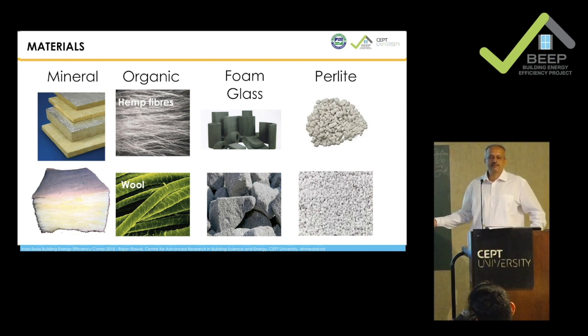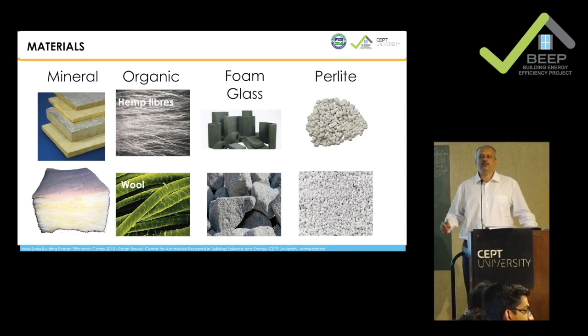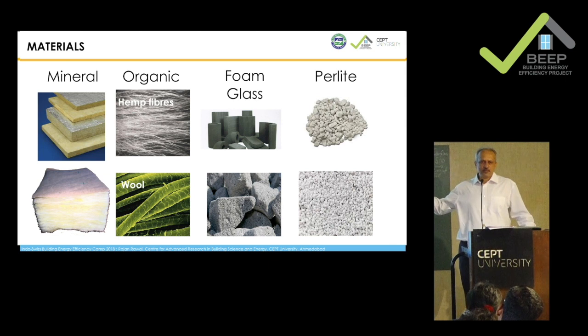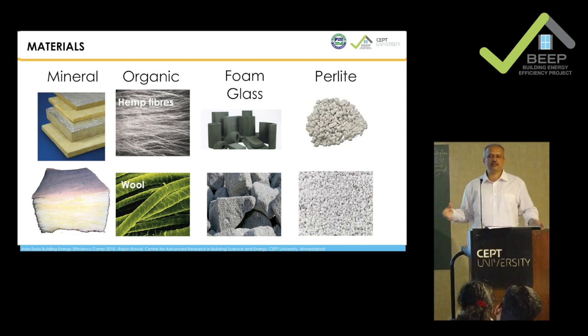So this foam glass gets used when you have to take a lot of load on the floor. Generally, it's an expensive material. We don't really use it on floors or roofs, because there are other materials available which can give us less heat transfer. But the advantage of foam glass is it can really take a lot of load, and you can put it on the floor.